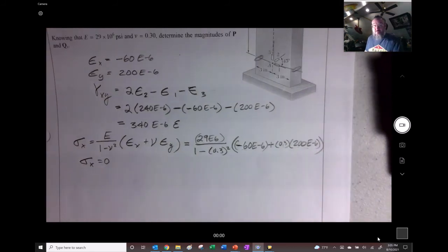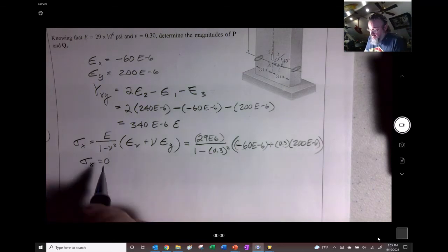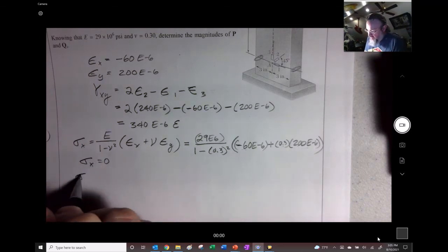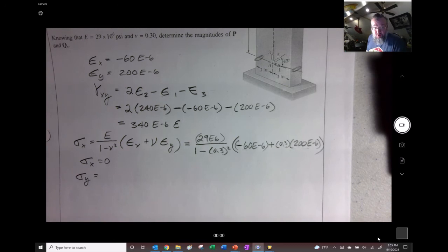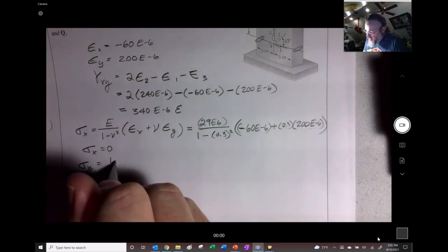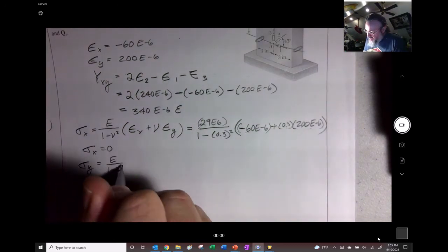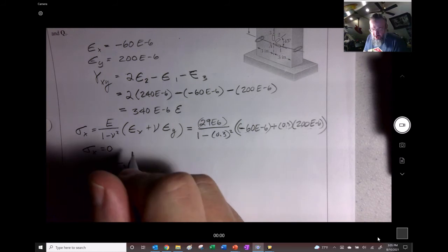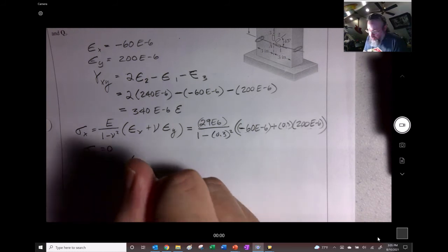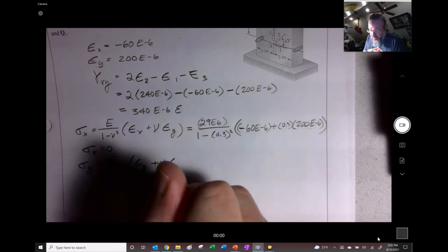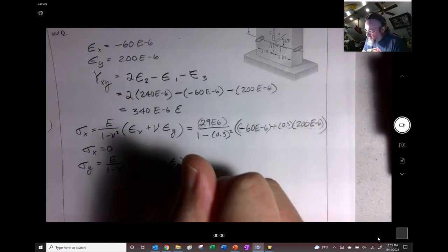It's really only going to have stress in this y direction, either by way of axial forces or from bending forces onto there. So we expect to get 0. If we didn't get 0, there'd be something wrong with our strain gauge. So here we go in the other direction. I just thought it was good to make that point clear by picking it apart and putting the numbers in.